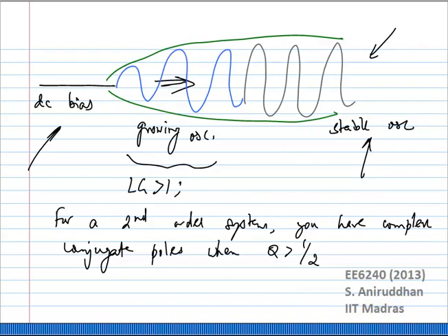Before you reach stable oscillations, the circuit needs to start up, and in that condition your loop gain needs to be larger than 1, or the magnitude of the negative resistance Ra needs to be smaller than the magnitude of Rp for it to be more dominant.